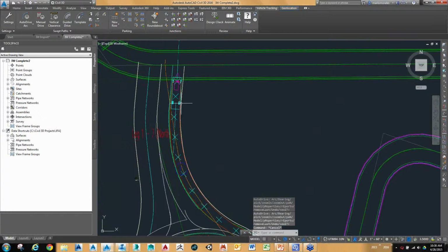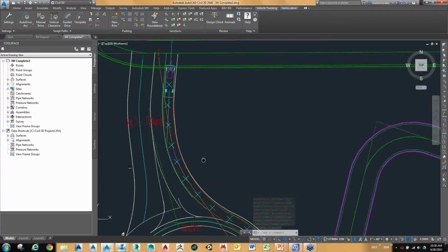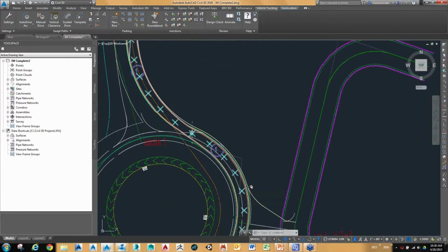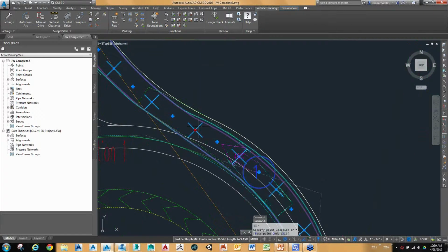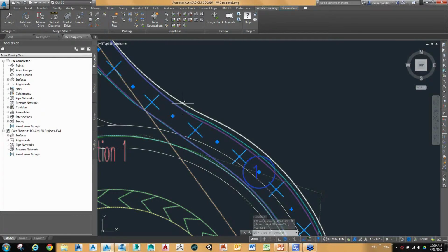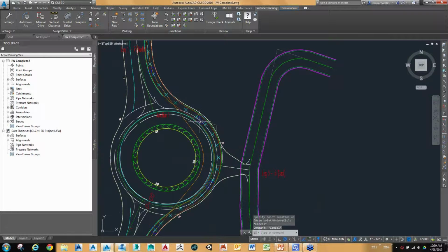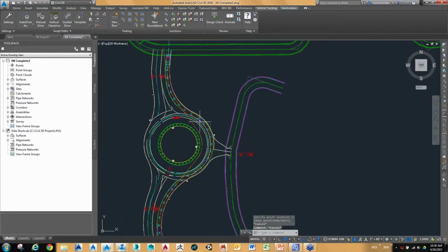So it leaves that path there, and you can see the vehicles there. It puts in all of my grip points, and when I select this, I have the ability to go in and make changes to the turning points. And notice if I go beyond where it can turn, I lose my outline. You just get a little red line. It just lets me know that I can't go beyond there. And then if I hit the little plus, it'll allow me to insert an additional point. So that looks pretty good.